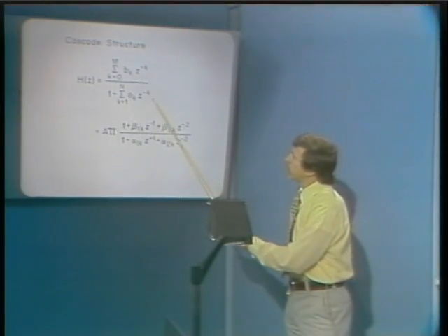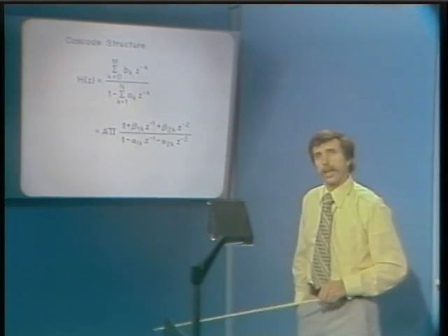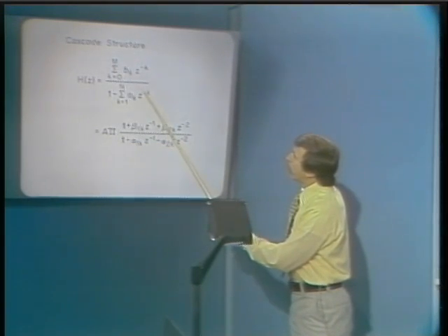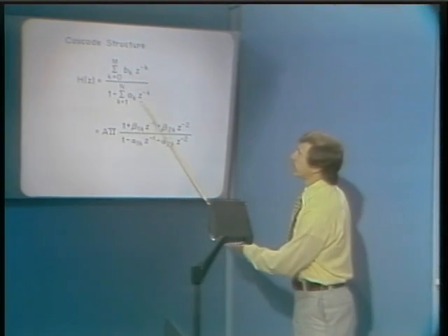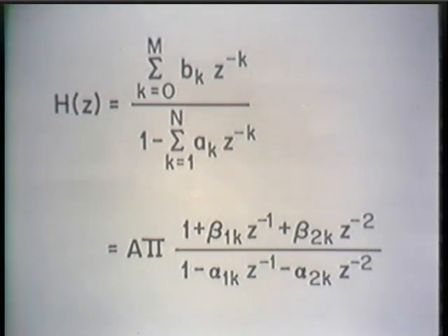And the statement which I'll make and justify in a little more detail at the end of the next lecture is that if I implement the poles of the system through a high-order polynomial, errors in the coefficients lead to large errors in the pole locations as compared with an implementation of the poles in terms of low-order polynomials.